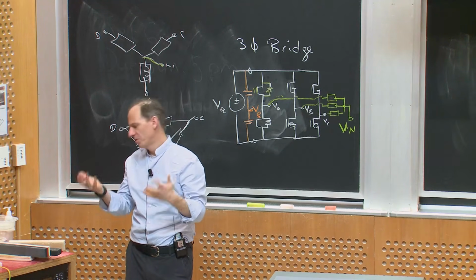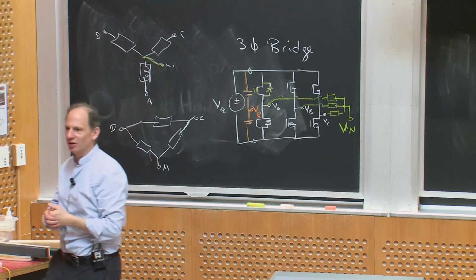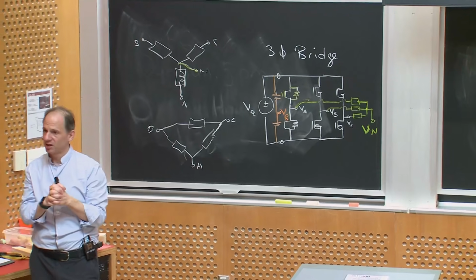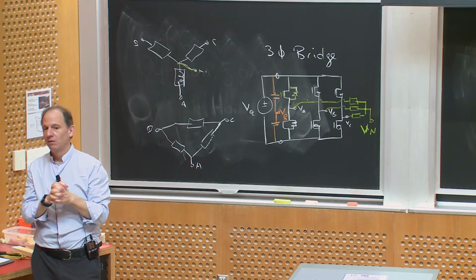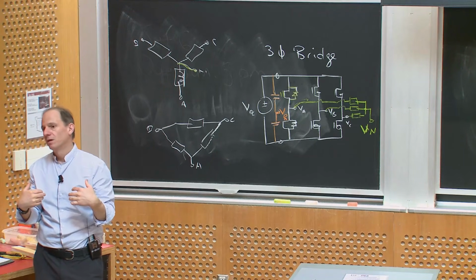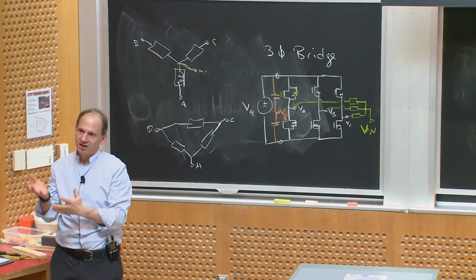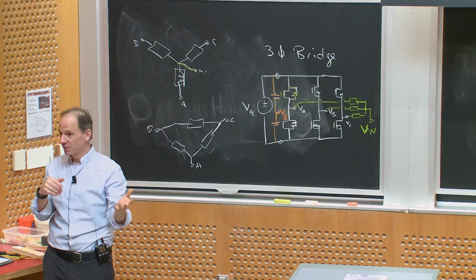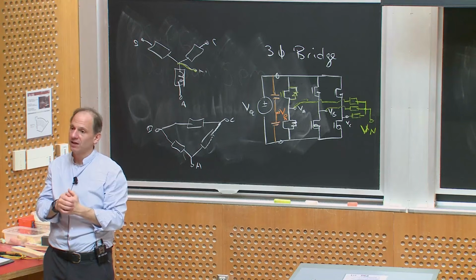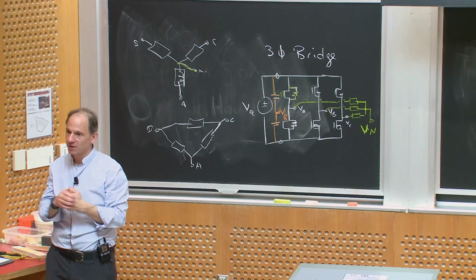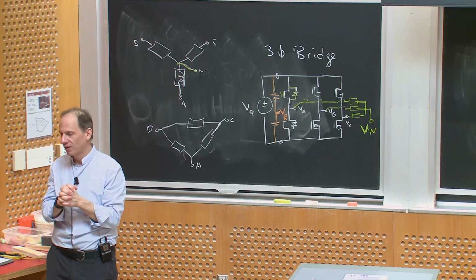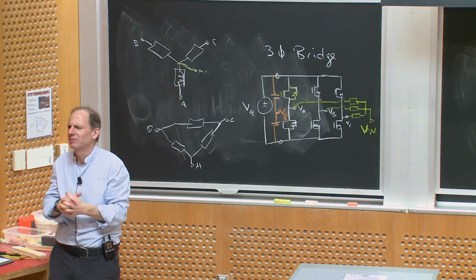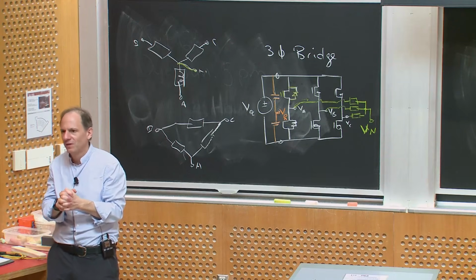And so, until maybe 5 or 10 years ago, it was most common to use IGBTs, especially at high voltage. More recently, with wide bandgap devices, people are starting to move over to mainly FET kind of structures, because you can get away with that, and it turns out to be lower loss. So whichever switch gives you less loss is ultimately what you want to choose to use.